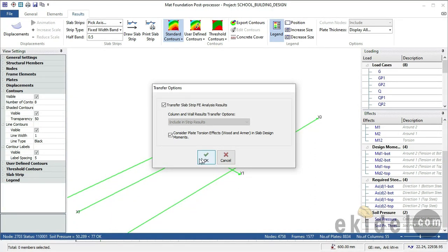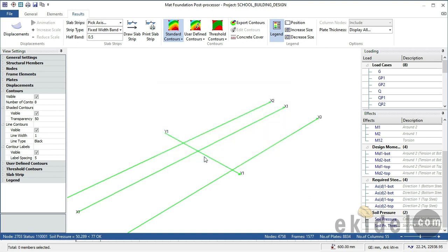So you have to click on this place here, say okay. So I'll click on okay and then wait for you to now transfer all the slab strip, which is the slab reinforcement, onto the model. Once this stage begins to read, you will begin to see the values here begin to read. So just hold on for it to start.